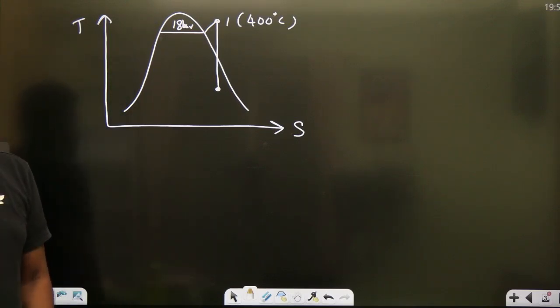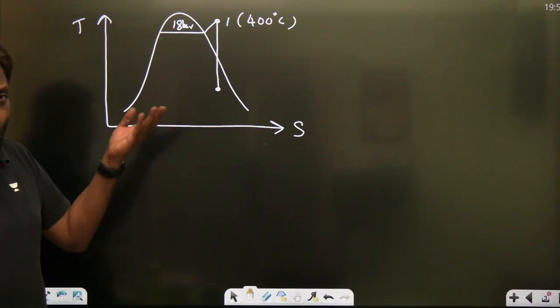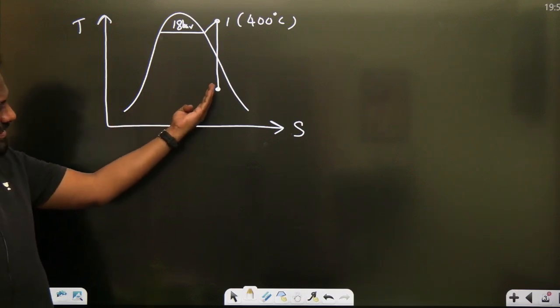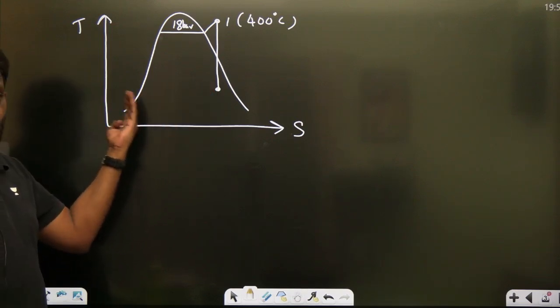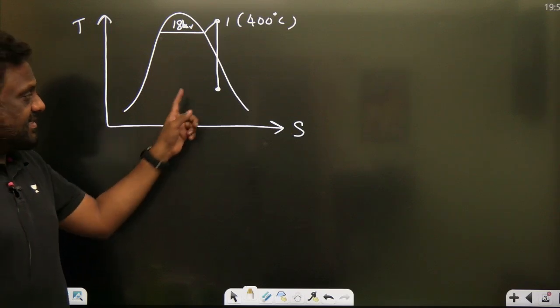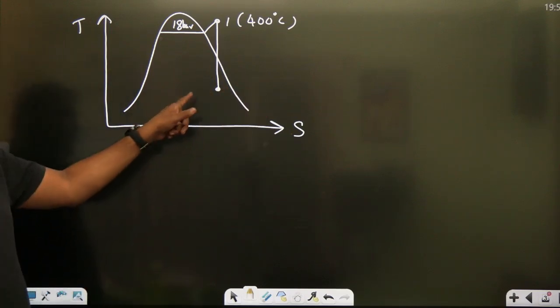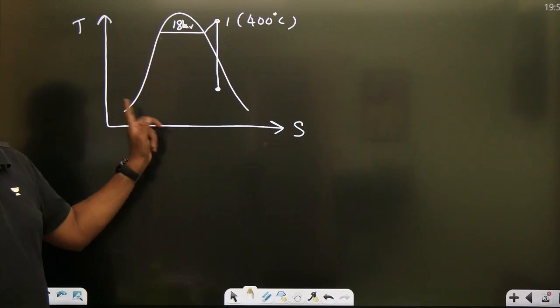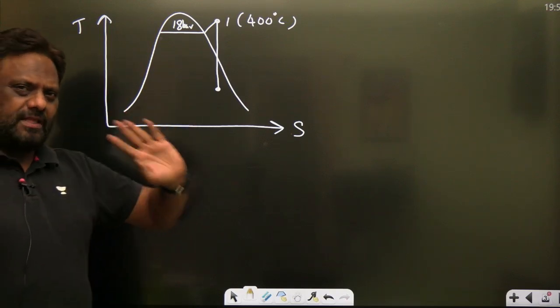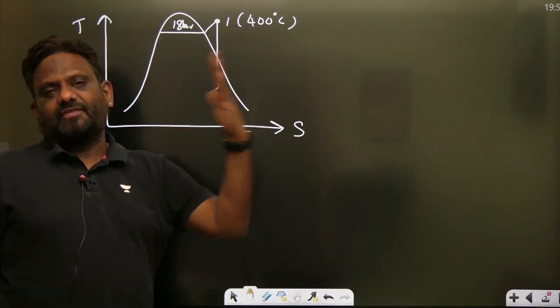Okay, right. Now, if the moisture content is increasing, the point will shift to the left. So if the dryness part, vapor part is increasing, it will shift to the right. So at the most, the dryness fraction, look at, it cannot fall below 85%. It has to be 85 or more than that. So let us try to solve this problem with 85%.